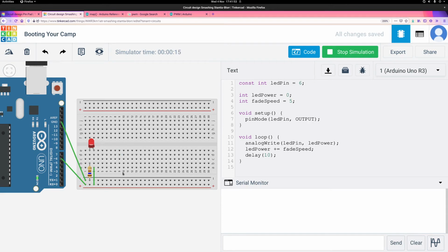So when the value that you give into analogWrite is higher than 255, it will start wrapping around back to the lower value again. So that's what we're seeing here in that little fading, pulsing thing. But that's not exactly what we want our program to do, because we want it to fade smoothly up and smoothly down. Right now it's fading smoothly up and then sharply down and smoothly up again. So it's going a bit like that.